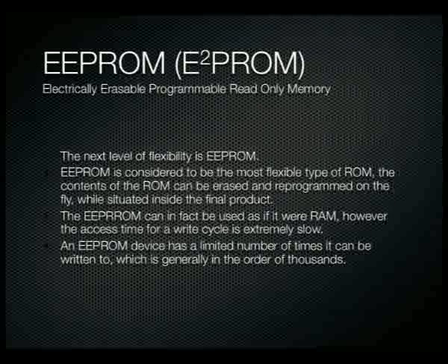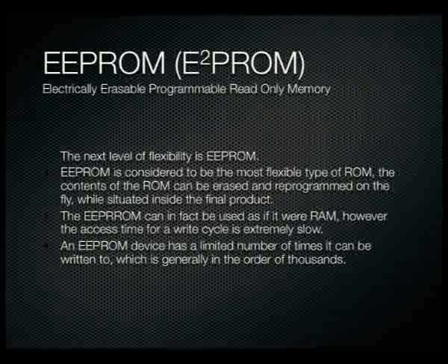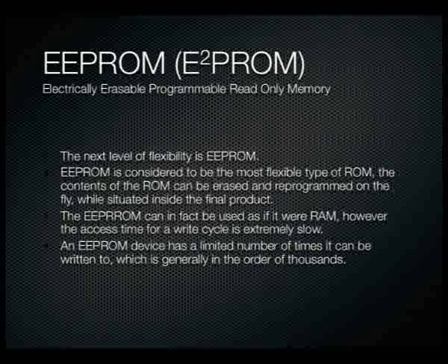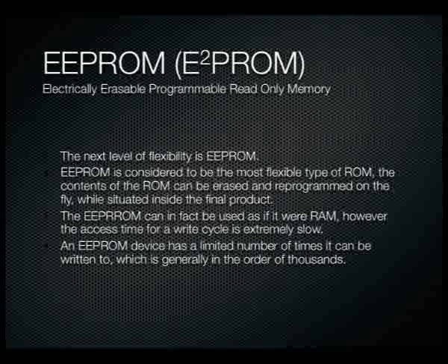So that's been the disadvantage of an EPROM and a PROM, is that you generally had to remove it from the device and either discard it or erase it and then reprogram a new one, or reprogram that same one you just erased and put it back into the circuit. So it always required a technician to do it. Whereas with E squared PROM, we can program it on the fly while it's still inside the circuit, so we don't even have to take it out. We just simply hook it up to a programmer, program it, and we're done. So this could be done by a technician or by an end user, depending on how difficult you've made the reprogramming.